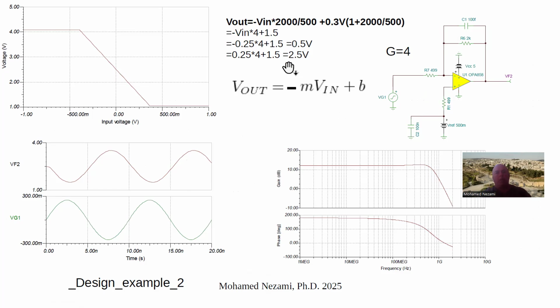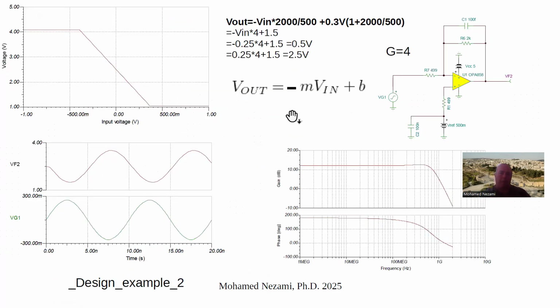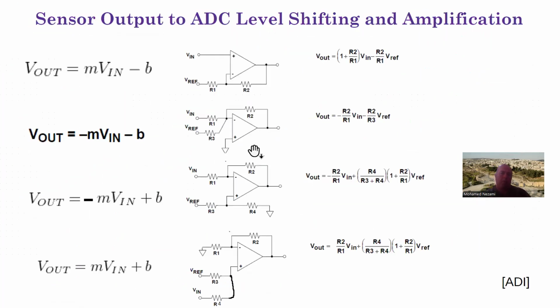Okay, so basically, as you can see, what we have to do with this interface business is always comply with this here. Even though I did this empirically, there's really a more systematic way to do it from this function. If we know the slope, so we know the sign, and we know the DC level, we can see which of these we need to solve, and then it's just two equations, two unknowns, because you've got two outputs. We're giving the input range and the output range.